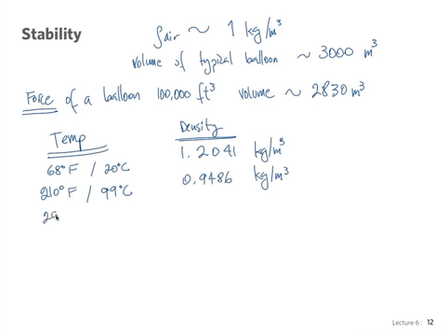And if we go even higher, of course the limit to this temperature is how resistant the material of the envelope is. They use some resistant nylon that is actually able to resist over 100 degrees Celsius, but the pilots choose to operate it normally at a lower temperature so that the material will last longer, but it's quite easily capable of withstanding temperatures of 120 Celsius.